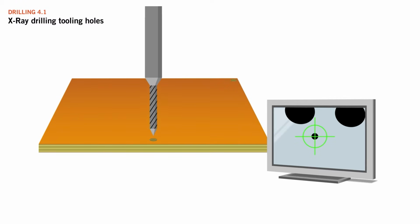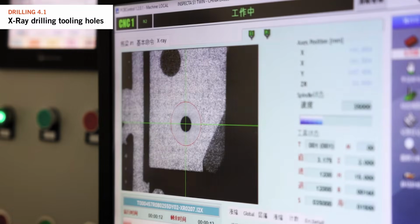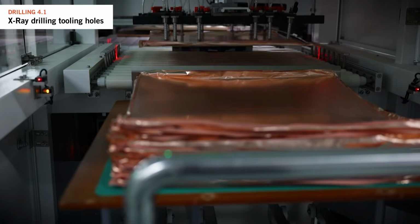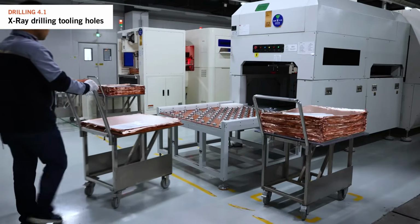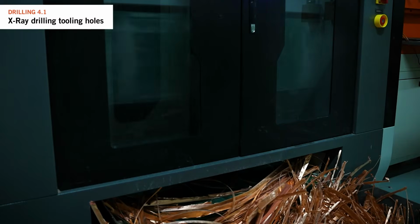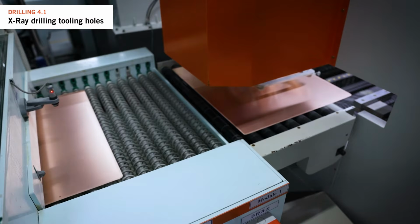We measure and record data to see how much the inner layer cores have changed in size during bonding. This information is then used to adjust for these changes in later processes, like drilling, to make sure the pattern accuracy requirements for all layers are met. In this stage, we also cut away the excess material all around the edge of the panel, as this is considered waste and to be recycled.